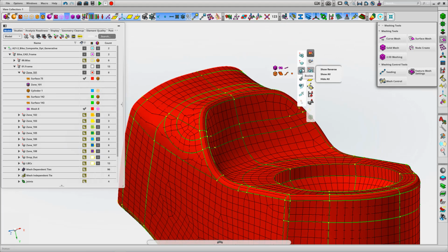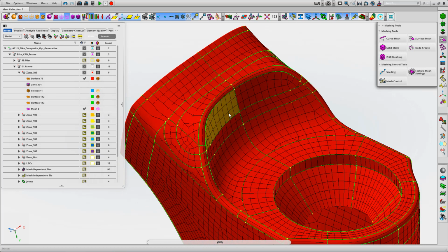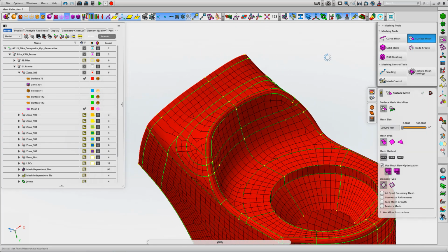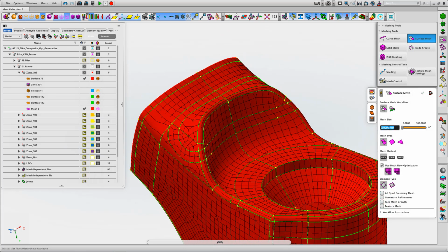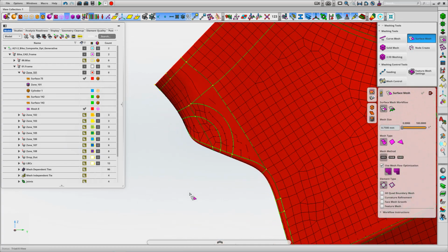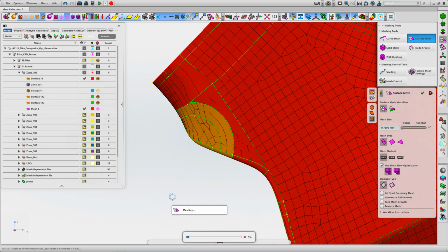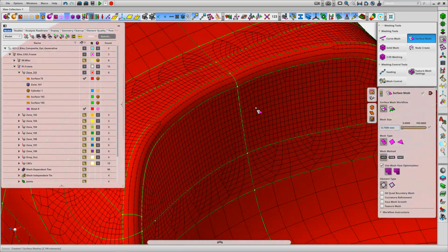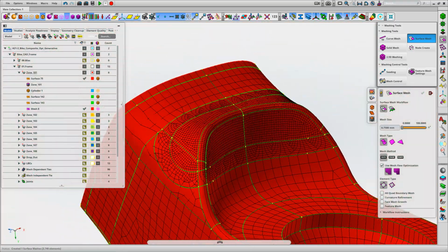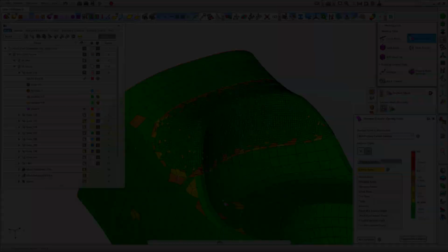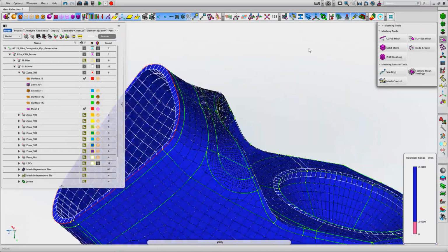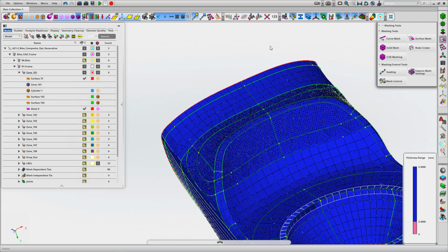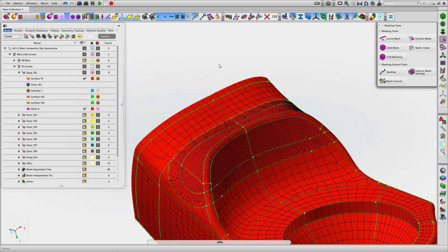A pretty simple example here, looking at remeshing for some of the detailed features. So we can see we've cut these faces out of the original zone definition, remesh based on a tighter element edge length, and then specify the faces in the model that we want to remesh. Okay, so we might be interested in a design change or some increased level of fidelity for this particular region. Many reasons why you might want to change the model, but all of those changes are updated automatically given Apex's generative update capabilities.